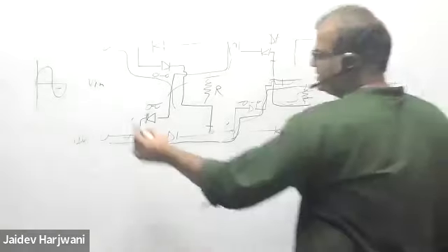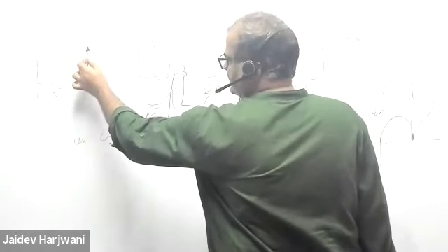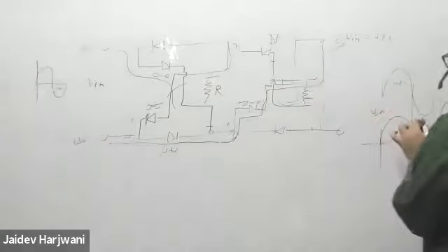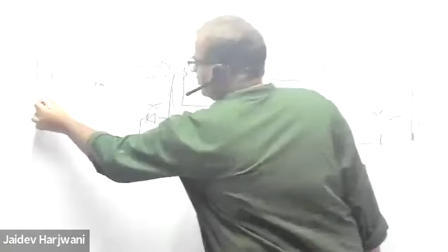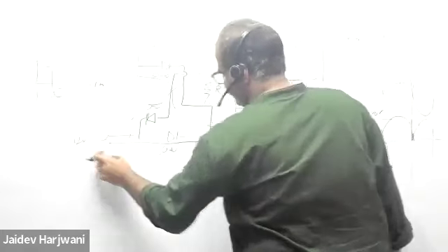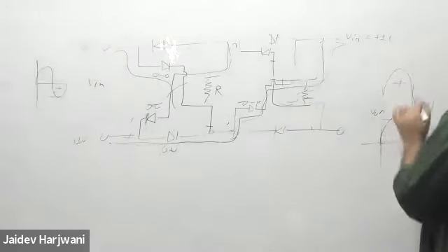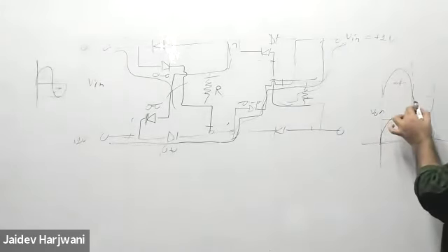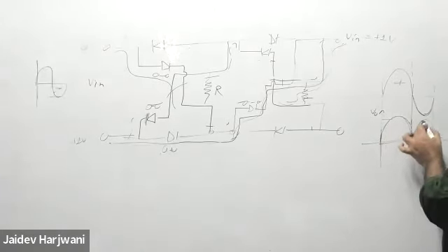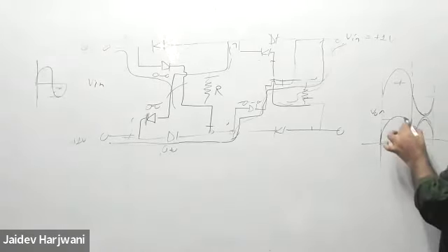Similarly, if you are giving -2 volt here, that means if it is 0, it is 2 volts, so 2 volts are coming here. If you give the peak value here, -5 volt, this becomes +5 volts. So it is coming here +5 volt. So for the negative cycle also, the output is in the same direction, like a full wave rectifier.